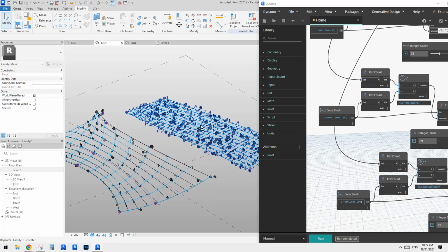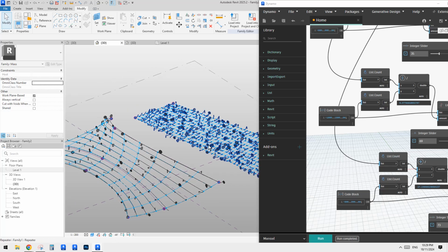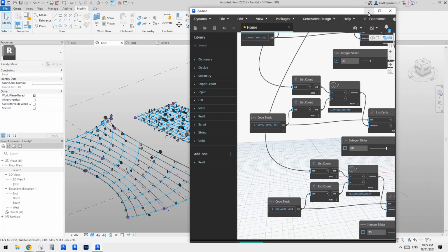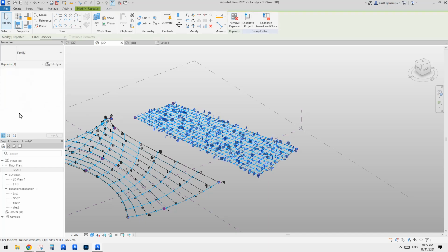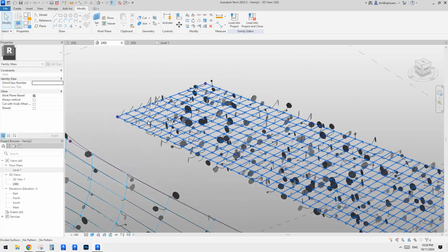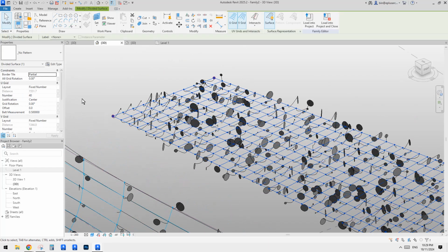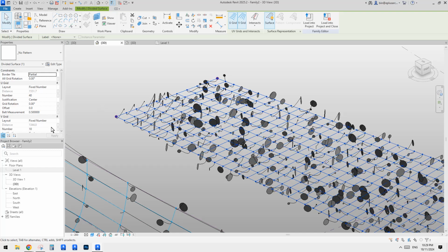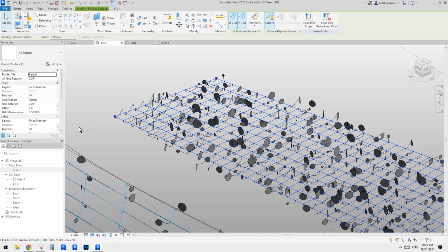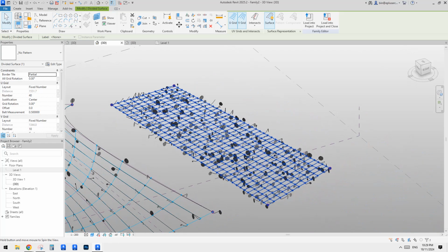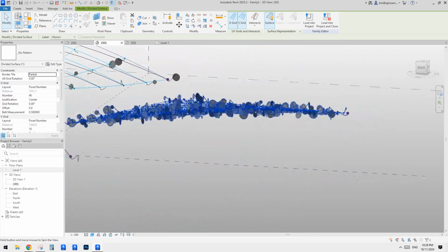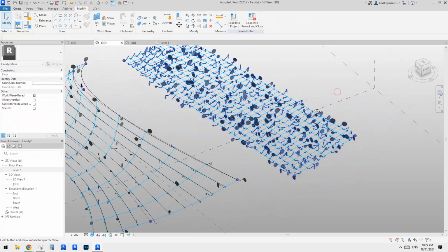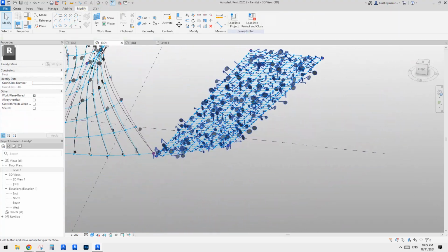So usually when you're still adjusting your device surface, or it's not ready for Dynamo, you usually just change this one to manual. In case you accidentally type a huge number for the device surface, it won't spend half an hour to calculate, right? Because you might have 100 here, and it will take maybe 10 minutes to do the calculation. And I think this is it.